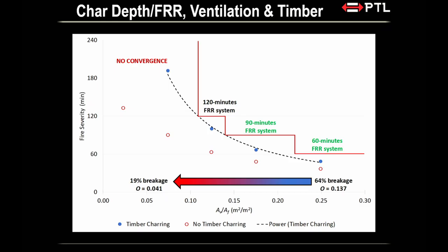If you encapsulate all the timber that was just being exposed, you collapse down to this red open circle. So you can see that this is an exponential relationship where a slight change of window size could mean a difference between 90 or 120, or 30 and 60. It's a huge difference for the cost of a building, really, right? But if you encapsulate everything, you're still going up, but you can almost see that this is more like a linear relationship than exponential. So really, that's the difference.